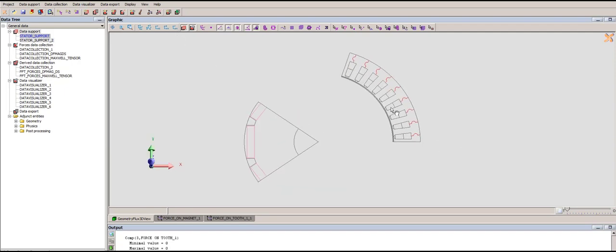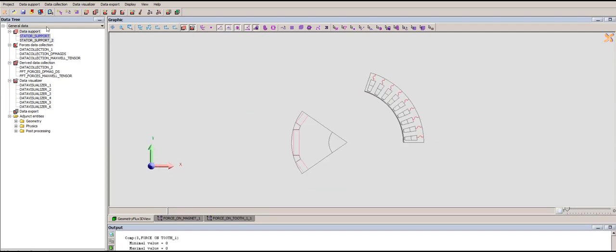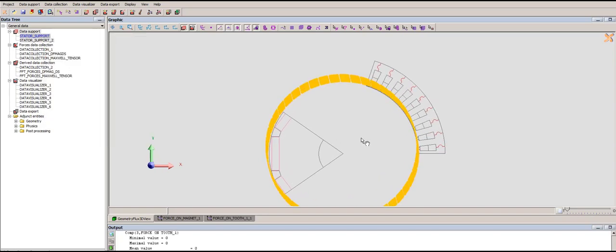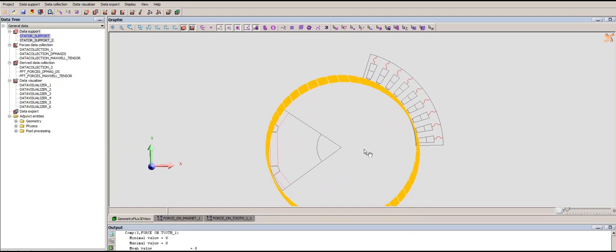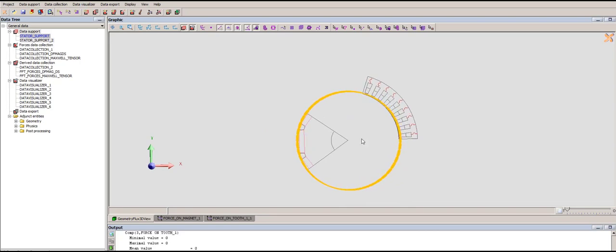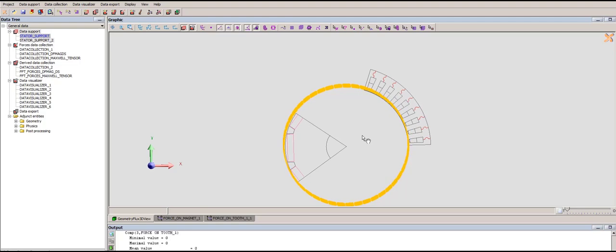Okay, so I have like a 3D one. So this is the support I can create for Maxwell Tensor. It's mandatory to be a pure cylinder here to use a simplified projective method. There is another method using the same Maxwell Tensor, but it's called a generalized projective method.